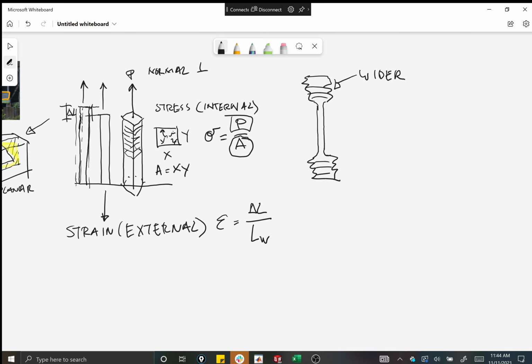Then there's a fillet here. There are structural reasons for that fillet, but it's also because we're bringing it down to a known diameter at an exact point, because we want to know exactly this length, which is the working length, the amount of this specimen that's going to be under tension.